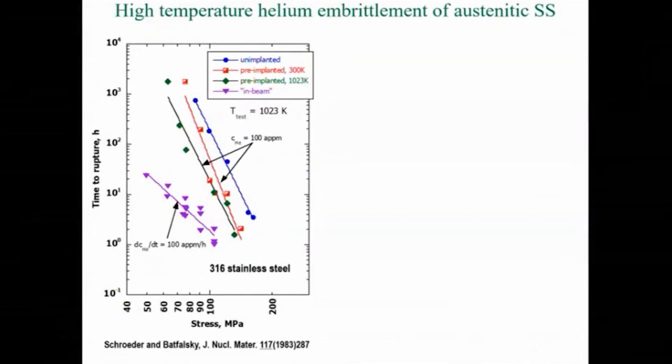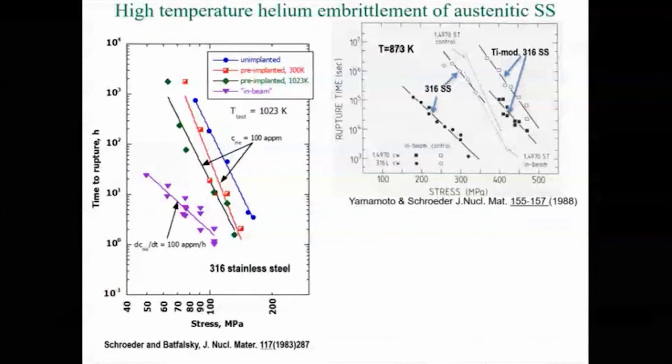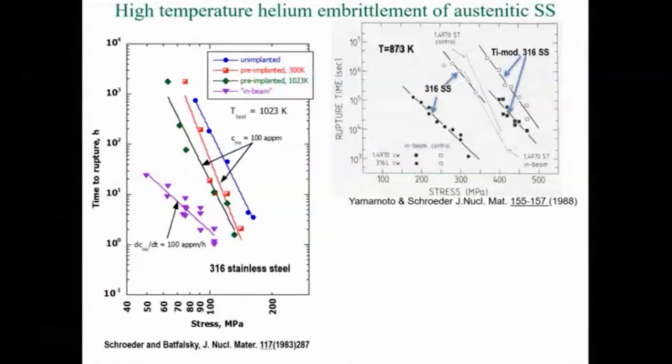These are the easiest tests to do. And unfortunately, there's too many journal papers that have used the easier way rather than the more reactor relevant type of an approach. So all that sounds like, what can we do to solve or mitigate this problem of high temperature helium embrittlement? The answer is in part by adding some second phase, the right type of second phase materials in there.